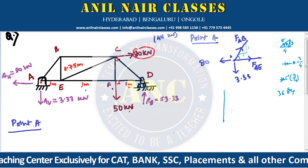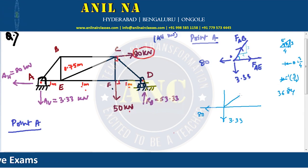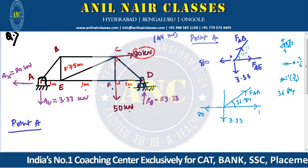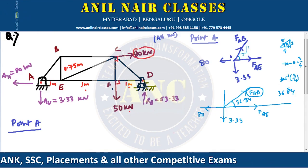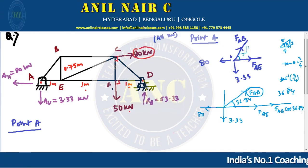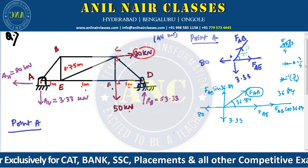So we can resolve this along the xy axis. 3.33, this is 80, this is FAB, and the angle is how much? 36.84, whereas this is FAE. So when this FAB is not in the x and y axis, rather it is making 36.84 with the x axis, this becomes FAB cos 36.84, and this becomes FAB sin 36.84.